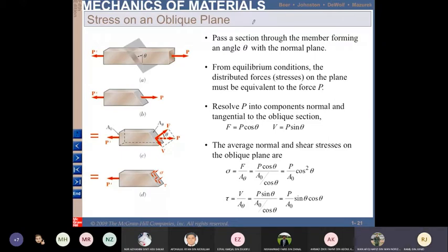So what happens to your equation or formula? Because we know that stress is equal to F over A. When the force that you apply makes an angle like this, what happens to this equation? Because the area has changed. So this is what happens to the equation. Stress is equal to F over A original cos square theta.